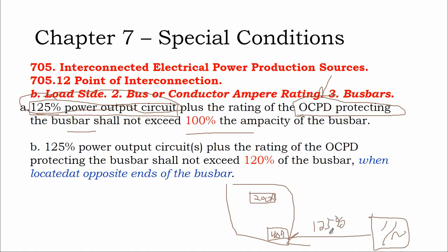So it's like the ampacity of the cable, but then you're just rounding up to the nearest breaker. So there's only like an amp or 2 or 3 difference between using the breaker size or using this 125% size. Just to make things simple, we got a 200 amp breaker and we got a 40 amp breaker. And that gives us 240 amps of power.